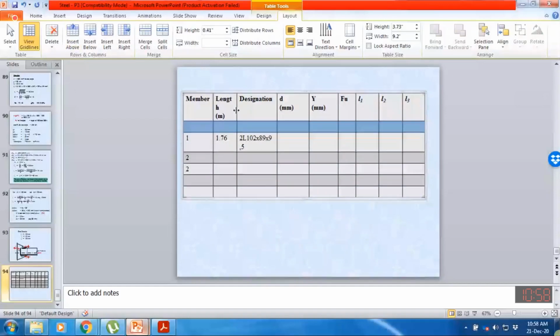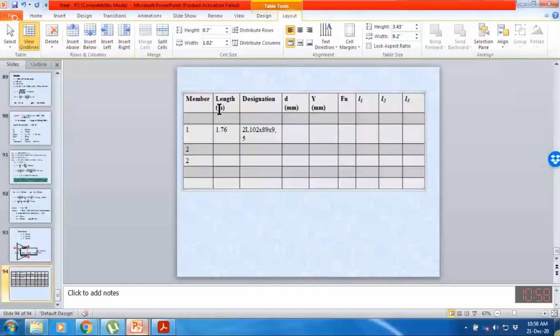Please remember that you need to design the weld for the heaviest member, and your R value, thickness of the weld will be fixed. So thickness of the weld, you are using constant value for the entire truss. So RW you are computing for the heaviest member.